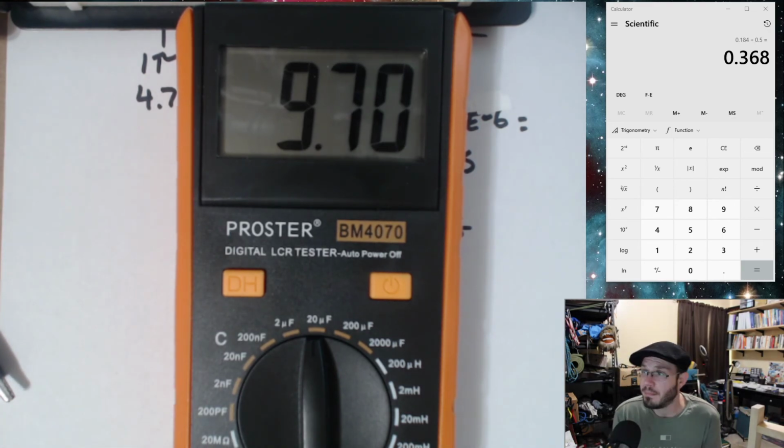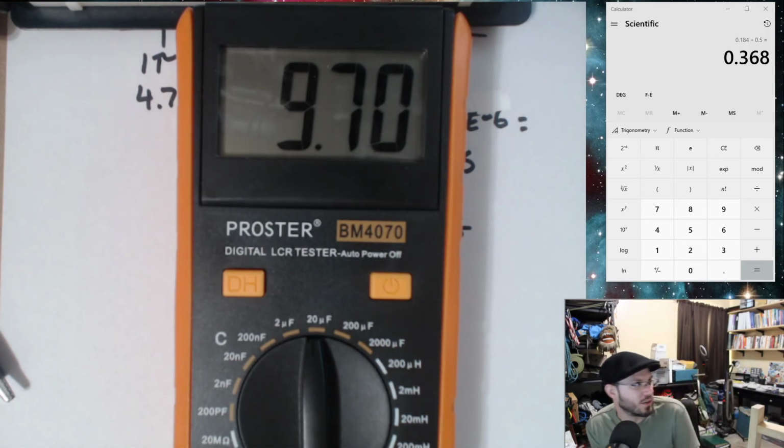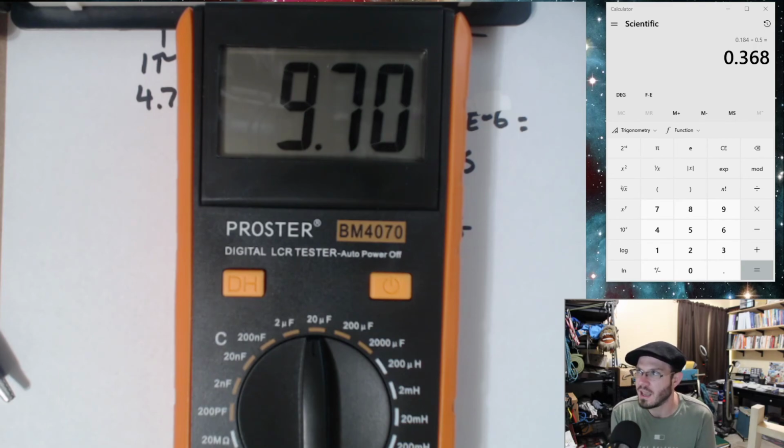In fact, this capacitor is going to charge a little more quickly. And sure enough, I noticed we were at 9.3, 9.6 volts, somewhere around there at that 5th time constant, which tells me we're actually charging a little faster than what we calculated. And that's perfectly acceptable for this.